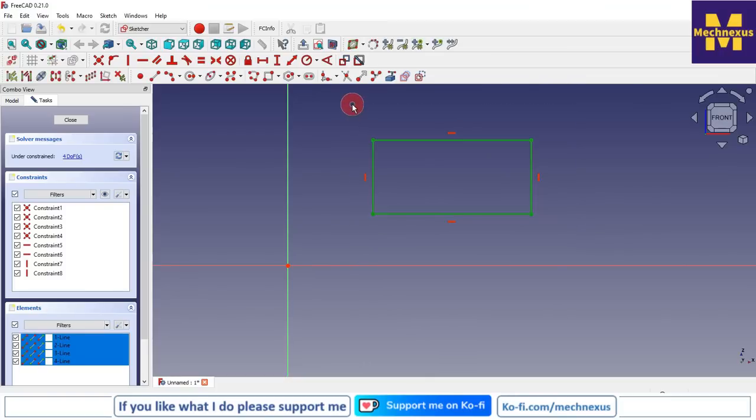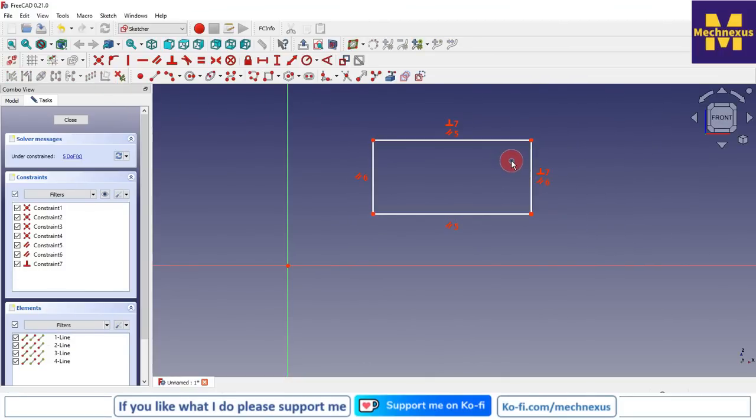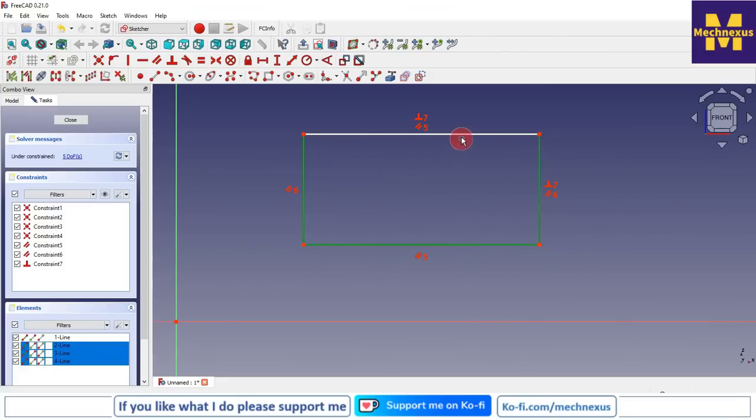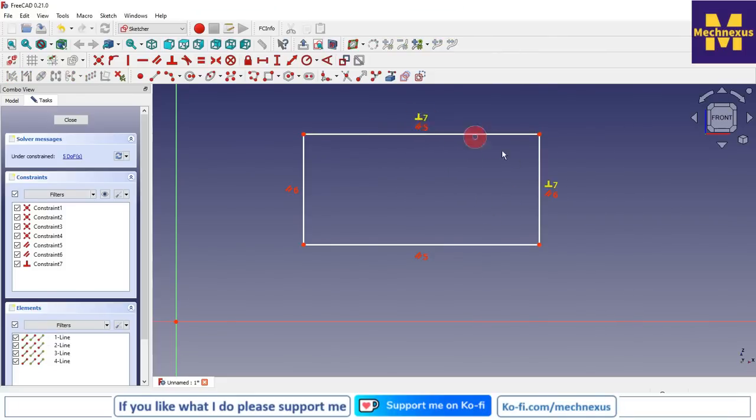Now if I select my rectangle and click on the axis alignment, then you will see that horizontal and vertical constraint got removed. Now this line and this line are parallel, and this line is parallel with this line, and here you will see that perpendicularity is applied. So this is the tool where you can remove the axial alignment.